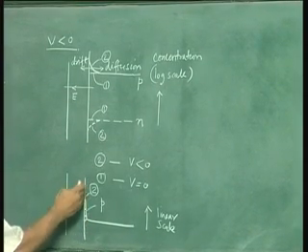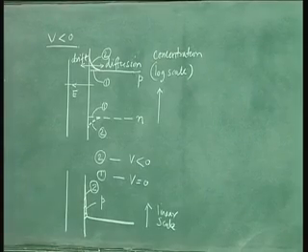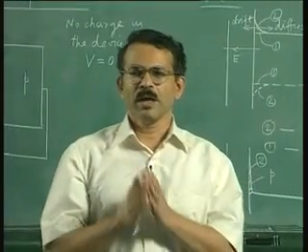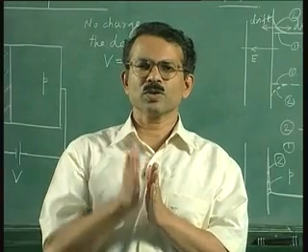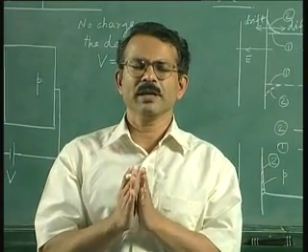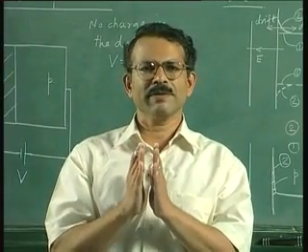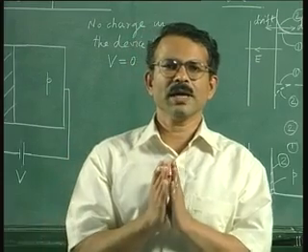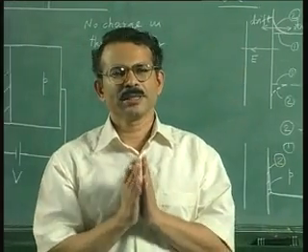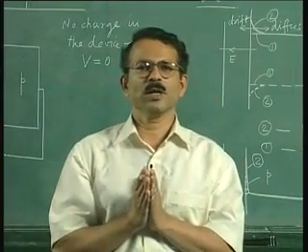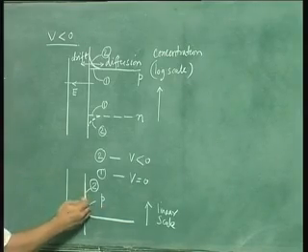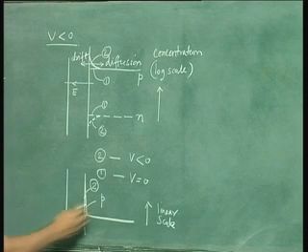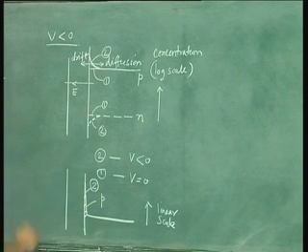Okay. Now this charge is almost like a sheet charge. A sheet charge is a charge that is very close to the interface and it is almost like a sheet, and the thickness of this charge is very, very small. Generally such sheet charges are because of mobile carriers, because mobile carriers can all remain attracted to the surface. They can move to the interface and then they can be held there by the electric field.